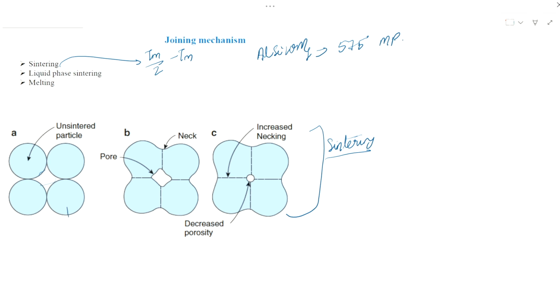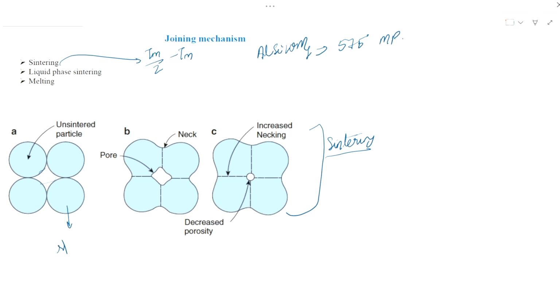Now, in the commercially available 3D printers, we prefer to use spherical powder particles. This is most preferable. Nowadays, a few studies are coming where we can use irregular geometry powder particles also. They are giving better mechanical properties, but this has not been commercial till now.